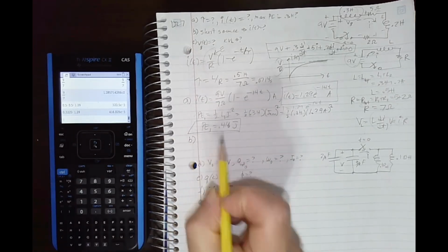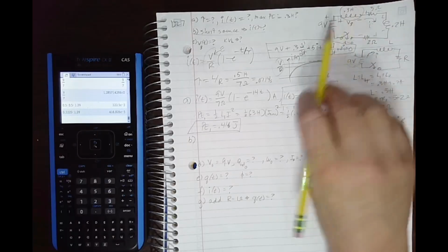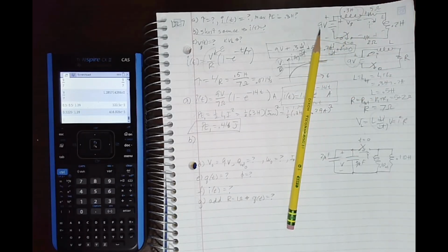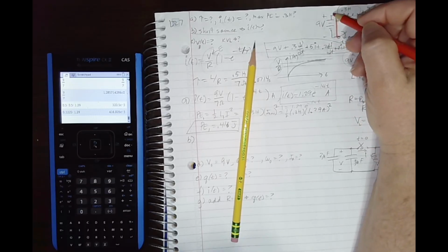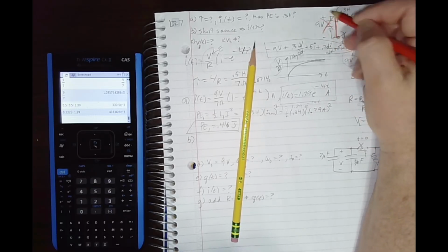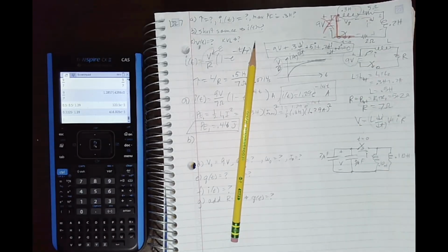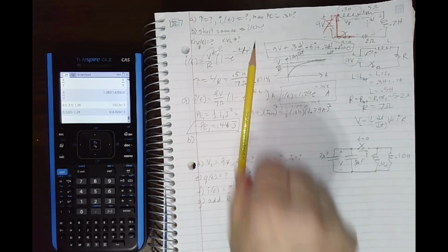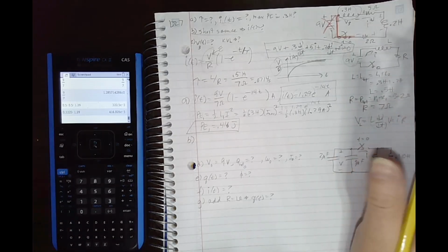So B, short the source, and now what's the current? Okay, so that's what I was talking about. We're going to take the source out of the circuit, put a short circuit across it, and so basically it's gone. All the current from it will go through here. It will not choose to go through any of those. The switch is still closed. And so now we've just got a loop, and all that's in it is passive elements. And so if the source hadn't been in there, we're going to assume it's been closed for a long time.